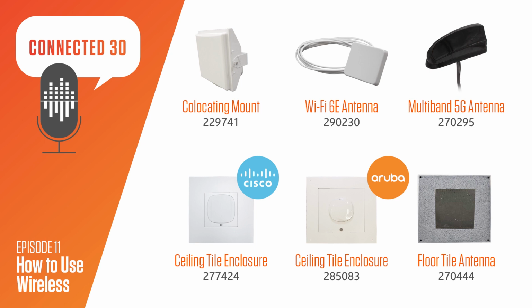Then why would I want to order an antenna for a spectrum that's not yet approved for use on an external antenna access point today, Dennis? The spectrum is approved. It's just that the antennas for use with external connectors on those access points have not been approved by the FCC. And that's because I can't control the power output or the dBi gain.